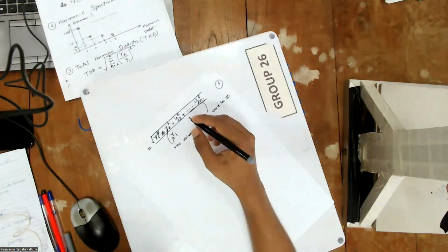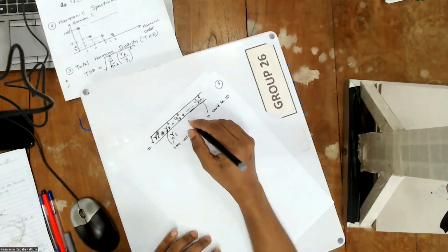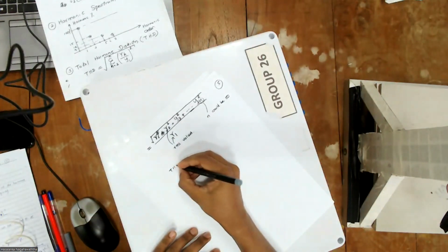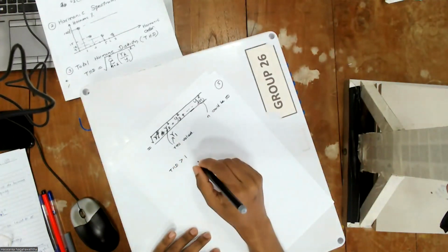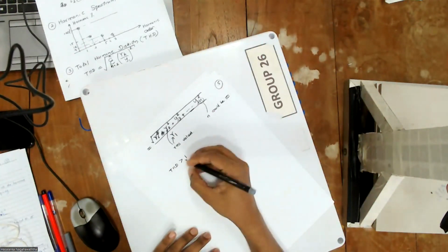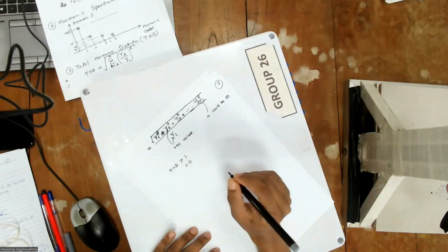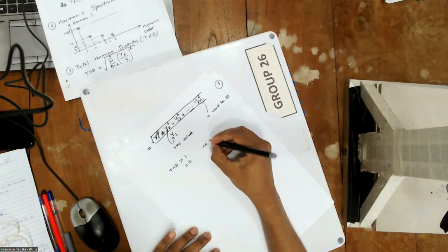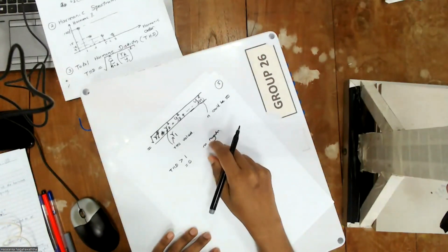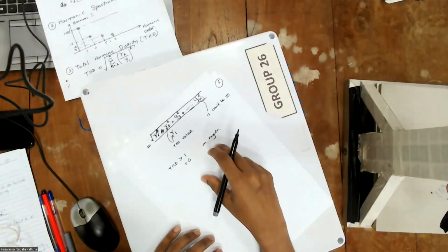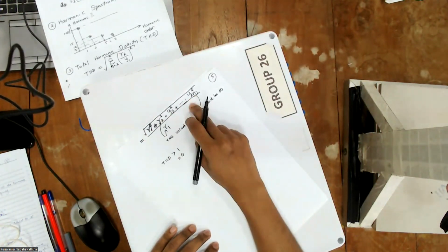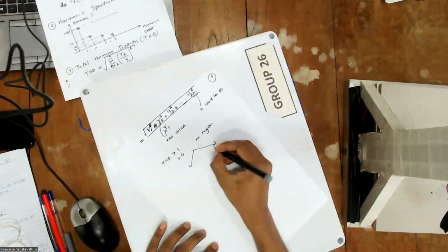From here what you have to understand is that the THD value can exceed 1, and it could be 0, but not negative. If you receive a negative number, that means you made some kind of mistake. But that is not applicable to decibels. And this general term, you can divide into two parts.